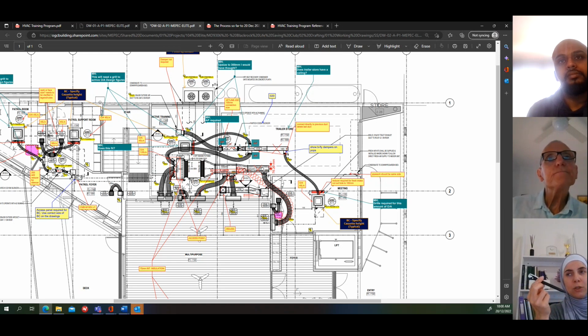Because all you need is just to slope the pipe. But in hydraulics, there are percentages that you need to take care of. Does this apply to condensate? It's not a regulation, I don't think it's a regulation, but we try to achieve at least 1 to 100.